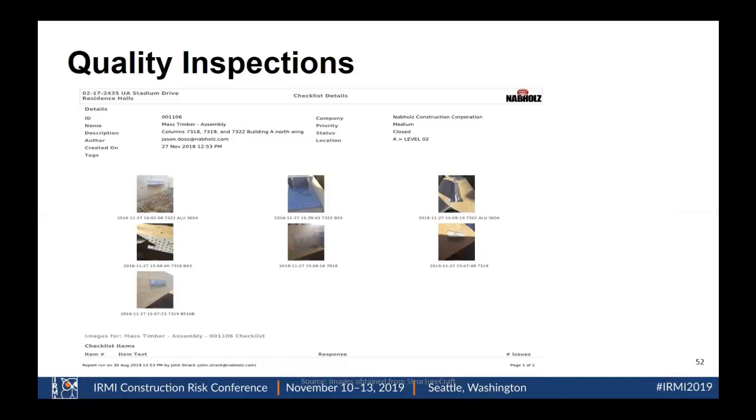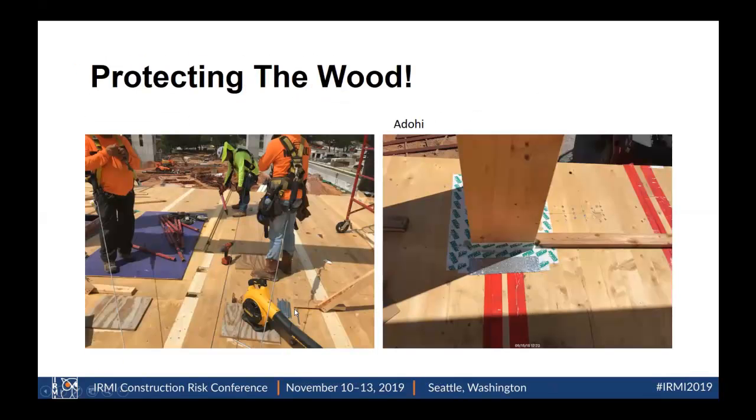This is more geared towards the risk management that we did and the quality management inspections that we did for making sure we put the right screws with the right brackets, etc. And then this one gives you a little bit more detail on what I was talking about on the spline board, where we were caulking at the spline connections, which every panel at the edges is routed out to butt to the other panel next to it, and that's where that spline connection's placed.